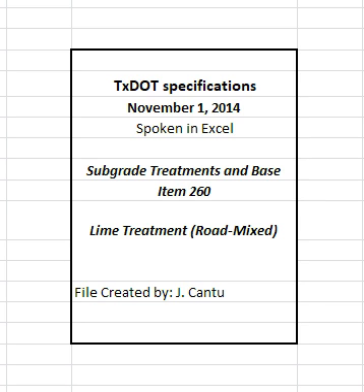5. Measurement. 5.1 Lime. When lime is furnished in trucks, the weight of lime will be determined on certified scales, or the contractor must provide a set of standard platform truck scales at a location approved by the engineer. Scales must conform to the requirements of Item 520, Weighing and Measuring Equipment.